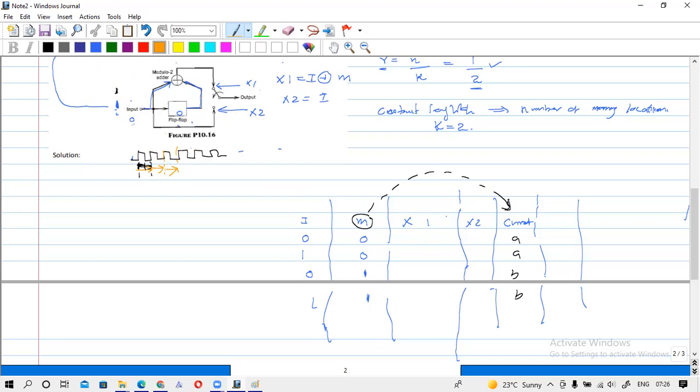Anyway, what I want to tell you is that this circuit is operated under a clock pulse train, so every change happens after one clock cycle. Say that at the next clock we get 1 here. These flip-flops are memory locations.